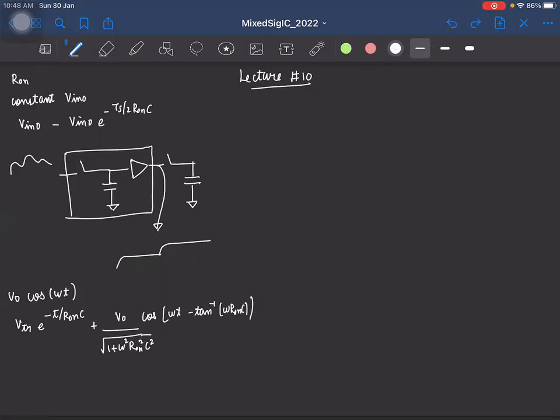And for the first switch, which was the NMOS switch, what did we do? To turn the switch on, we need to connect the gate to VDD. Okay, so if this is my input, we saw that the on resistance of the switch was inversely proportional to the VGS minus VTH.